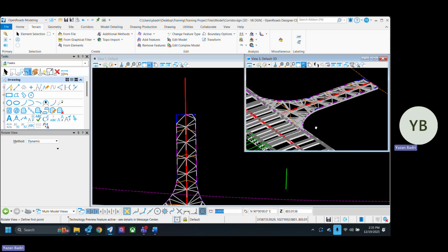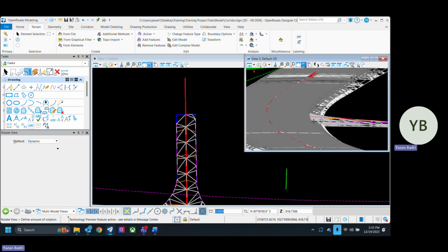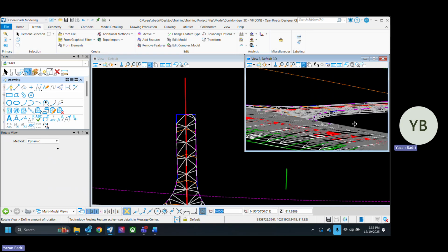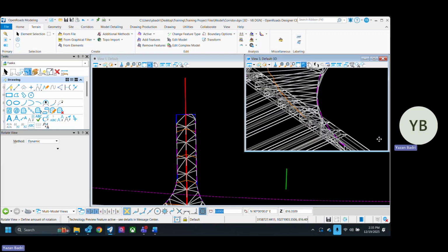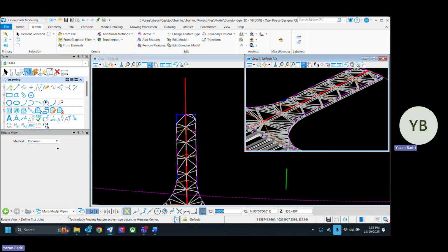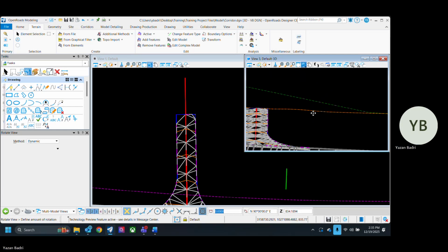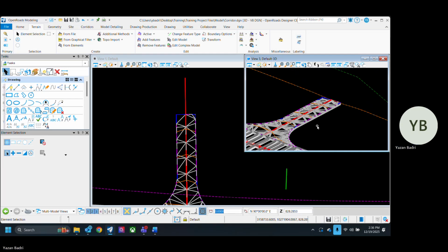Here's a driveway. Cool. So the edges of the driveway are a projection from the center line profile. Yeah, they're tying into the edge of pavement profile and tying into the profile that I designed for this driveway. This is the manual way, and this is the same way we do an intersection. Imagine this, but 4 legs. Okay, same exact thing.